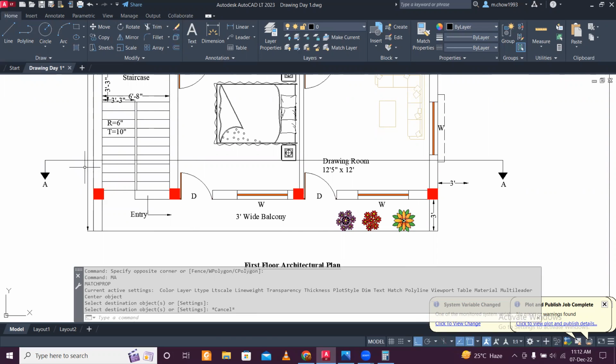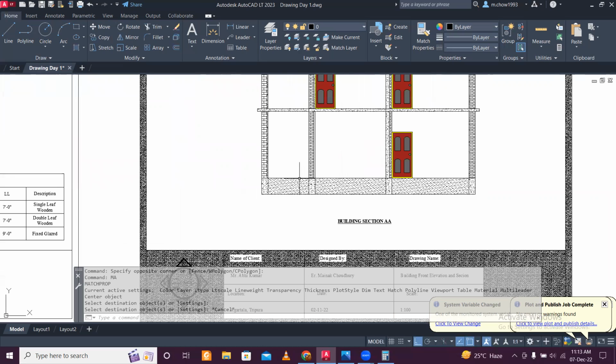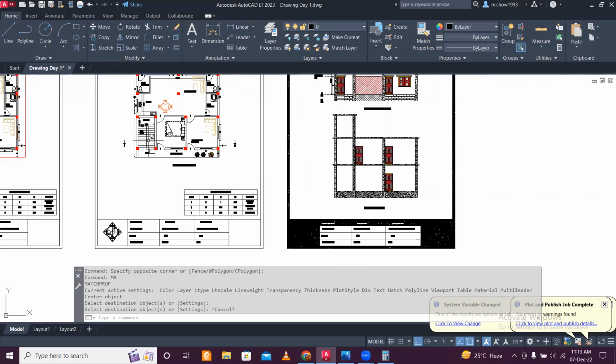So if you are cutting this portion out completely, we will not be seeing the first one, two, three, four risers. We'll not be seeing the first four risers, and we'll be seeing the remaining risers and also the landing portion of this particular first flight. And for the second flight also, one, two, three, four, and five, these five stairs will not be seen as well. So that's the concept. So we'll start from here. We know the riser is 6 inches. So